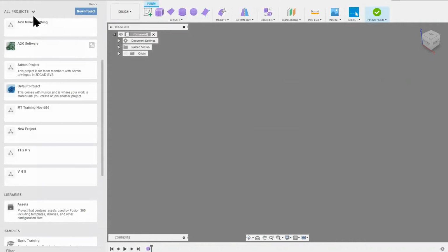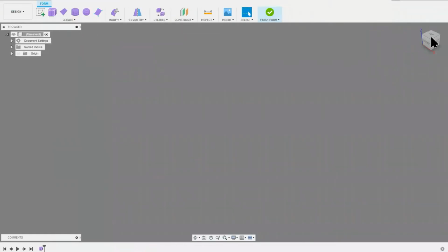Like I said, it's effectively where we save our files directly to the cloud, if that's how you choose to do that. As I mentioned, we can work in offline mode with Fusion 360. Up in the very top right, you've got a couple of little icons. You'll notice we've got the option here where we're signed in to our 360 account. But under this, the little clock icon here, you can see that I've got an option where it tells me that I'm working online presently.